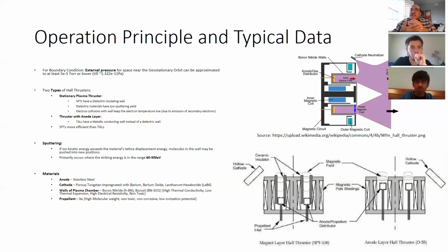But the keeper structure is important because I think there's a backflow of ions that hit the cathode, and the keeper structure gets eroded very quickly. The reason I'm saying that is that we're trying to look for the critical elements of the design as far as materials degradation is concerned. So for this hollow cathode design, its lifetime, the degradation that happens, and the structural and thermal performance would be important to figure out.